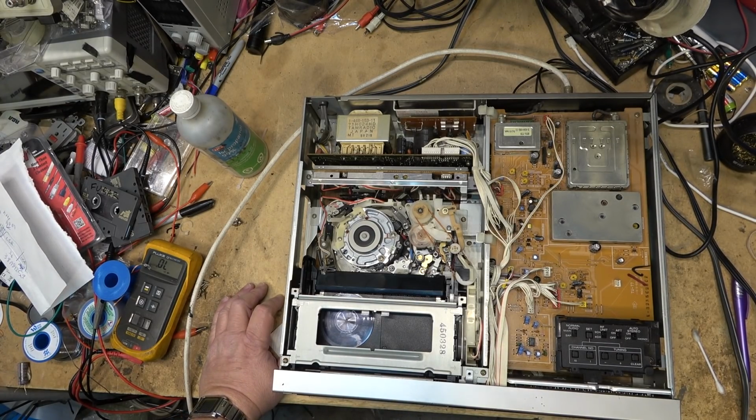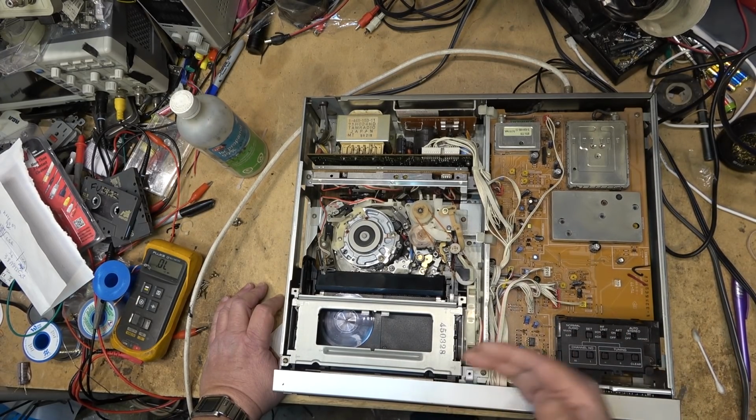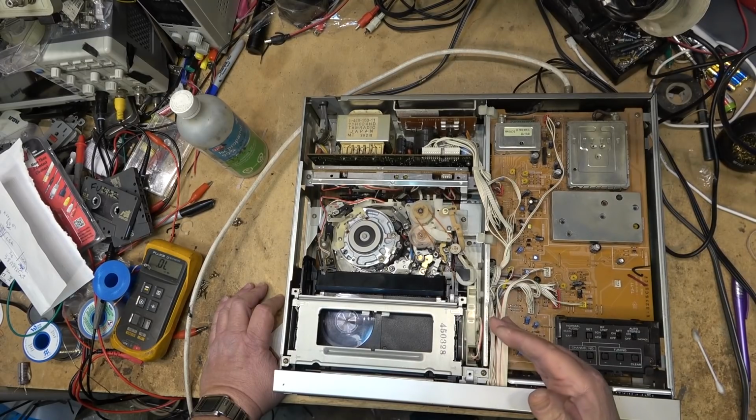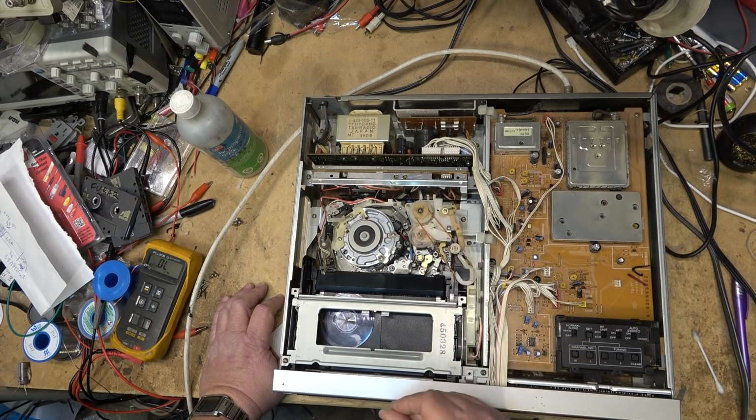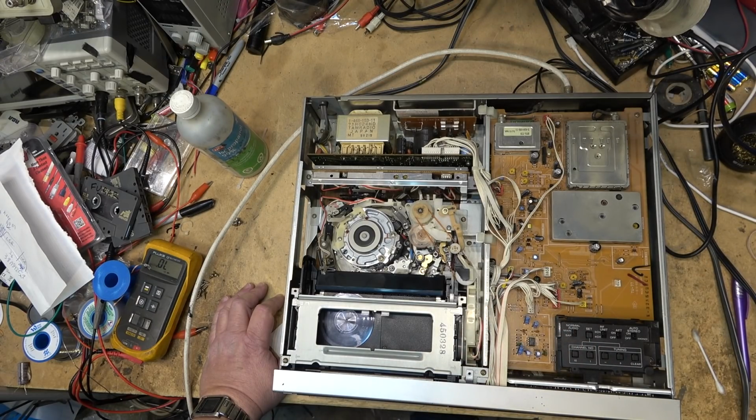It was a way to be able to basically control everything with basically two wires, well, one wire. You had a reference voltage pulling through a pull-up resistor, pulling it to your reference, and each switch was grounded through a resistor, which would drop the voltage a specific amount.